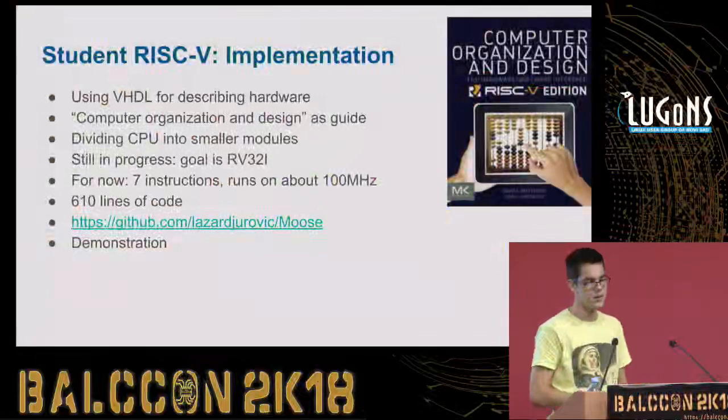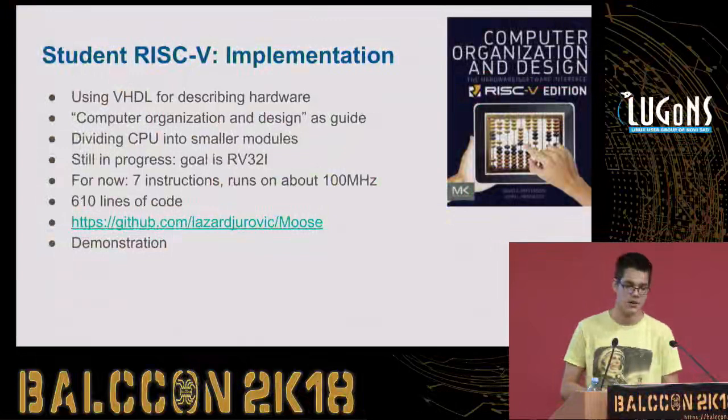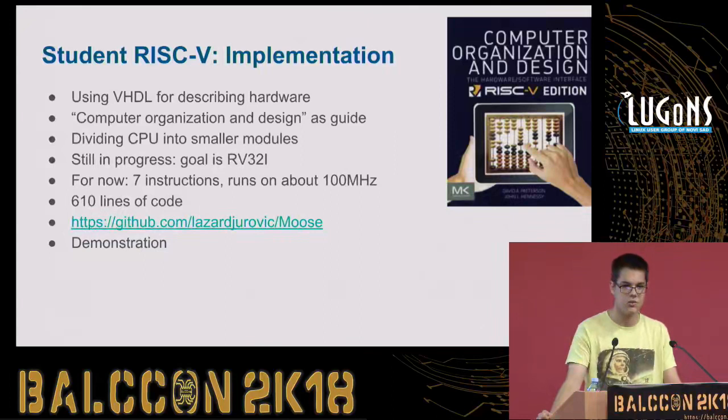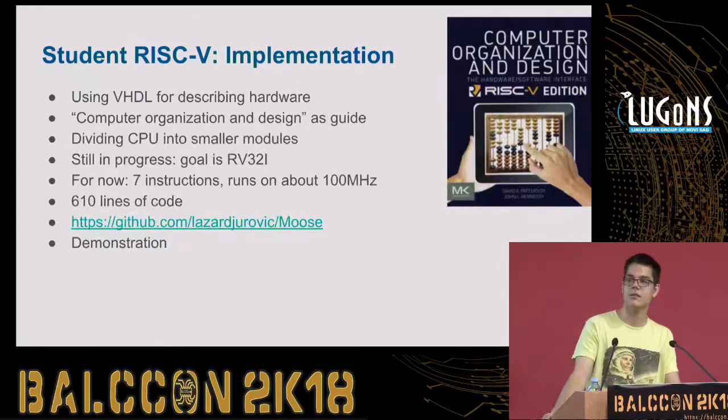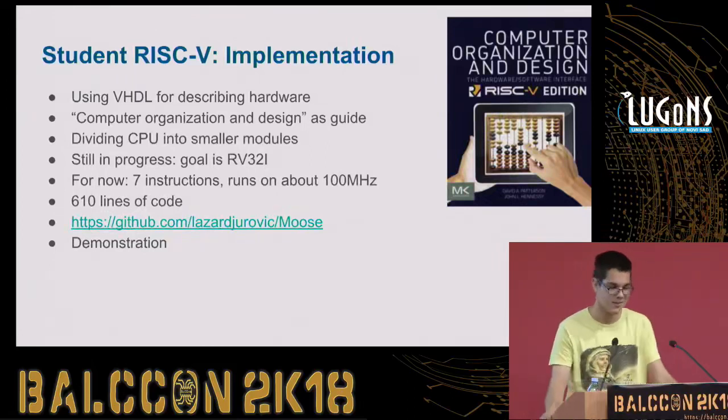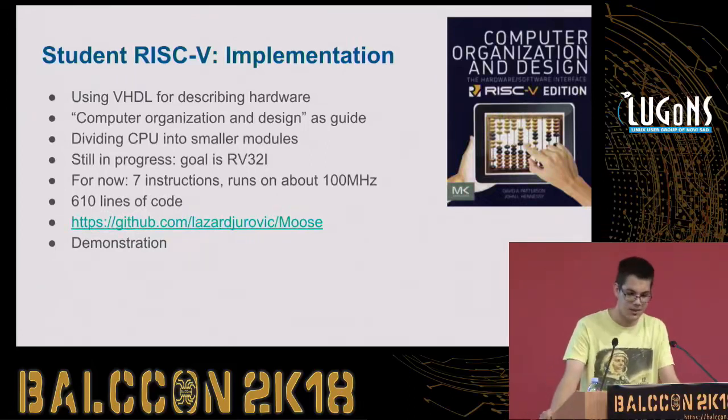I'm using VHDL, which is a hardware description language, and it's not like a programming language. You describe how electronics inside of the FPGA will be connected, and I divided my CPU into smaller modules, which are all described in this book. I divided it so I can make a module and then make a test bench for it, and if it passes, it's good. If it doesn't pass, it's not. So this simplified the development.